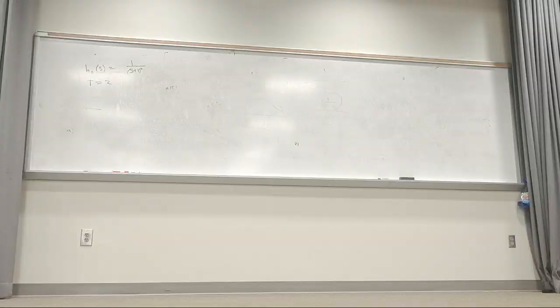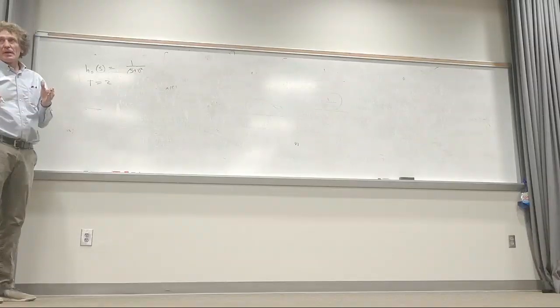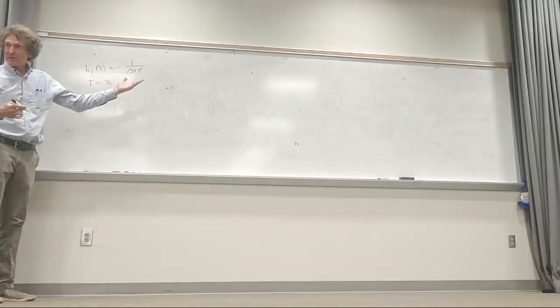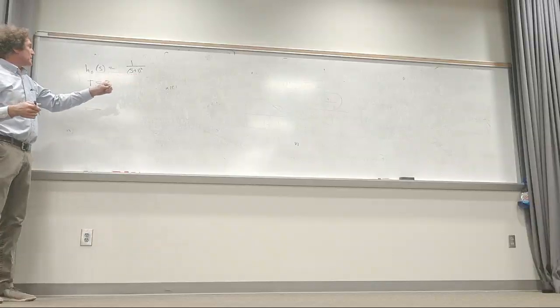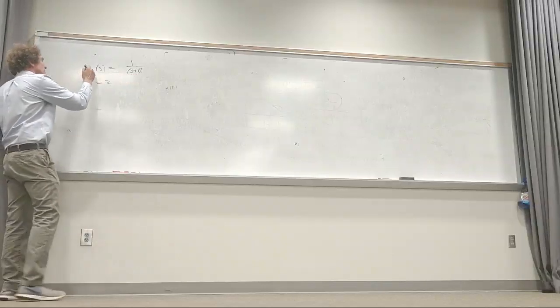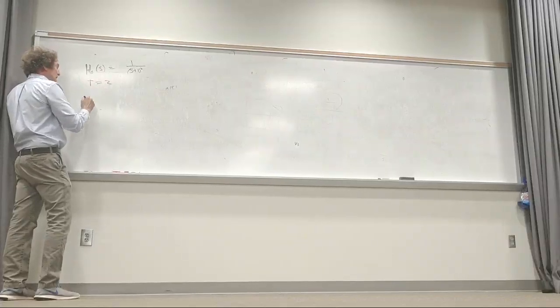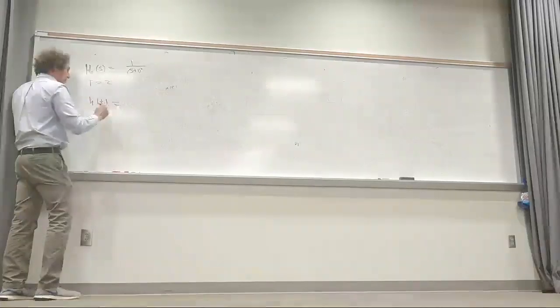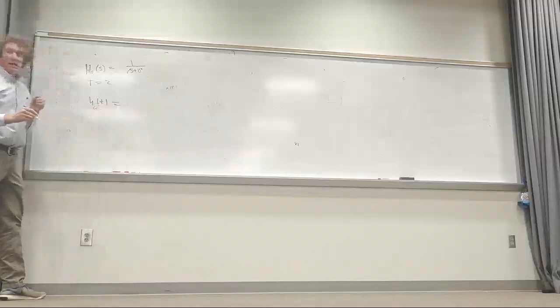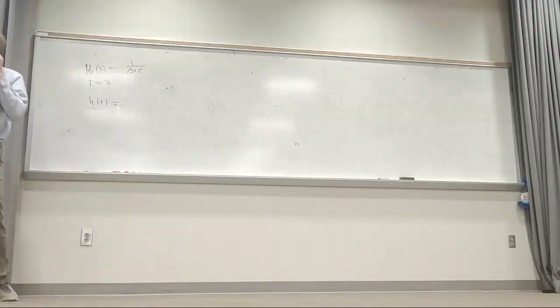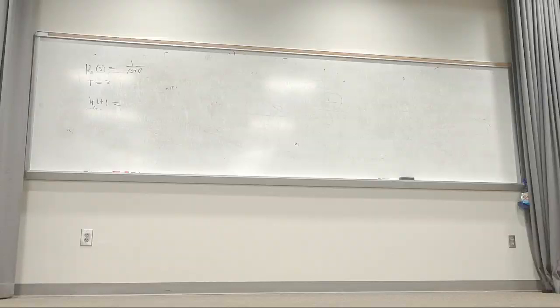So if you're going to do this, first, if you're going to do impulse invariance, that's the one I just did. All right? If I showed you this, what do we need first for that? If this is H, capital H of S, right? And T is 2, then what is my H of T? Take a look at that. H A of T. Well, what if it was 1 over S plus 1? What would the output be in the time domain? E to the minus T, U of T, right?